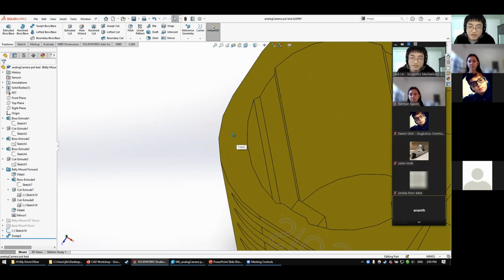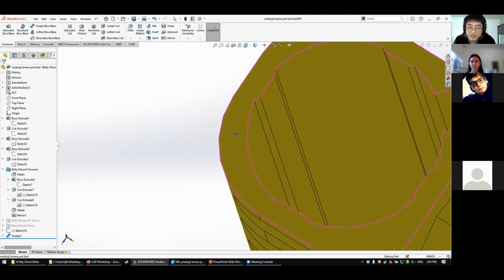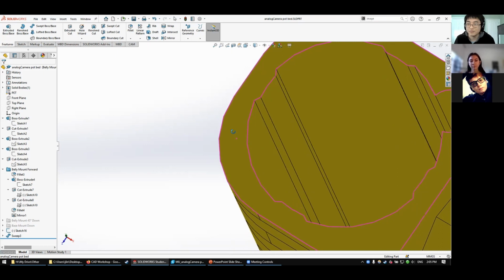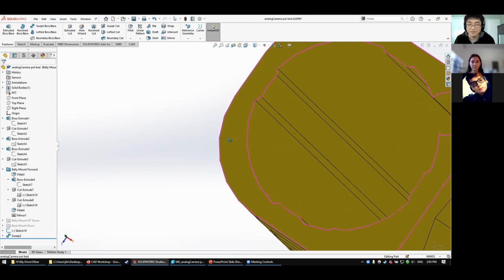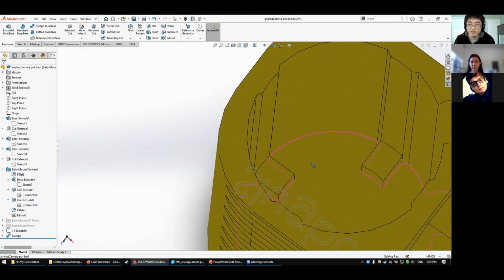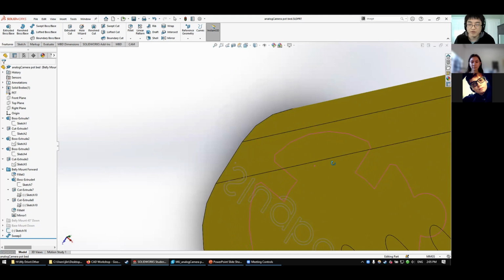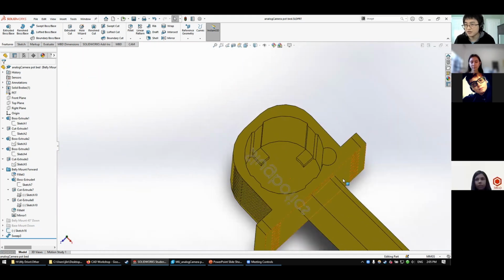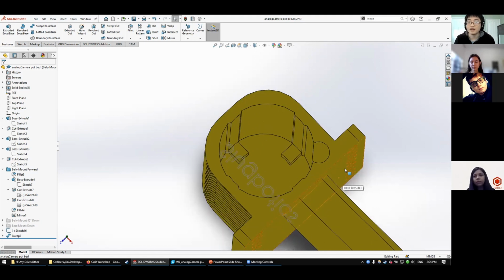Notice, it's hard to see, but there's a little pink plus sign right below my cursor, which is currently a blue arrow in a circle. I'm rotating freely around that point. If I select a different place in the bottom of the trench, then I'll rotate freely around that point. So depending on where you click middle mouse, you will freely rotate the camera, orbit around it if you might, at a different location.